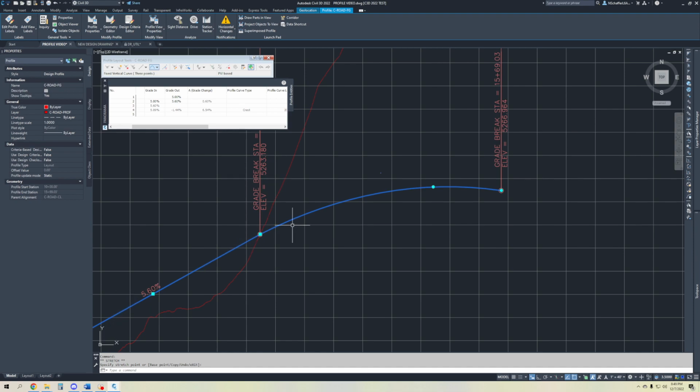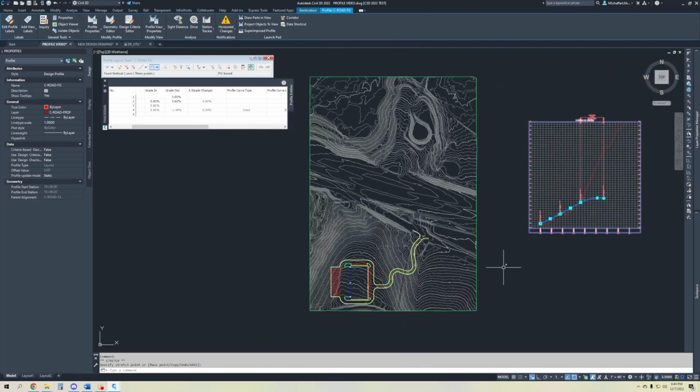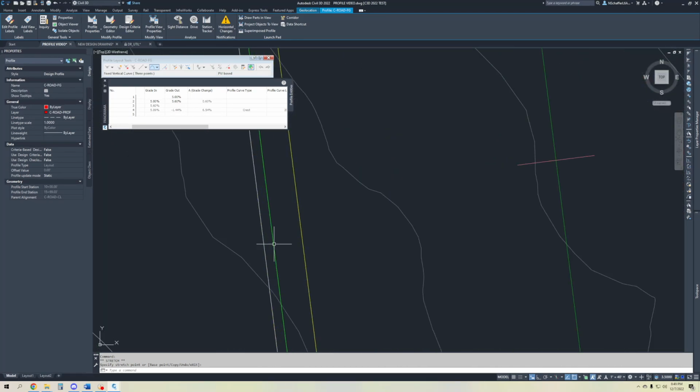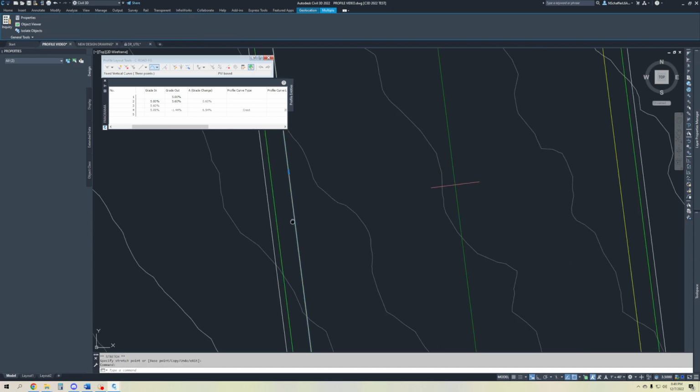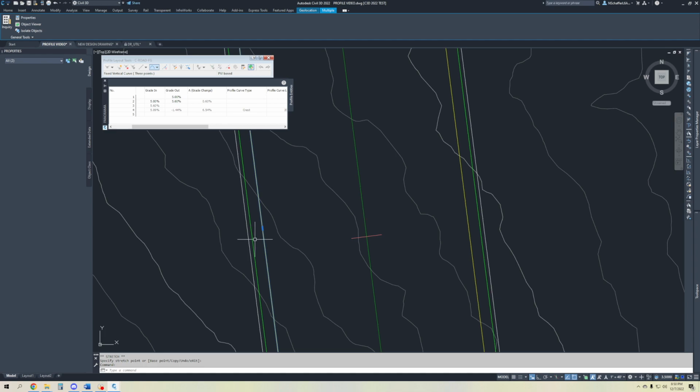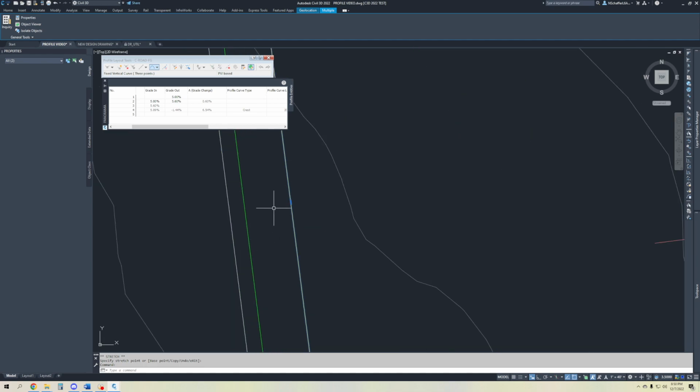You can use these as, let's say, the center line of the road. You could make this your curb lip line, which would be the very start from the asphalt to the curb and gutter. Your lip is going to be that, and I'll show you really quick. If this is the front of your curb where it's going up and down, that's going to be the front face of curb, top back of curb, and this is your curb lip. This would be asphalt here, this would be concrete, this is your gutter, this is where water would be flowing. That's going to be your lip.